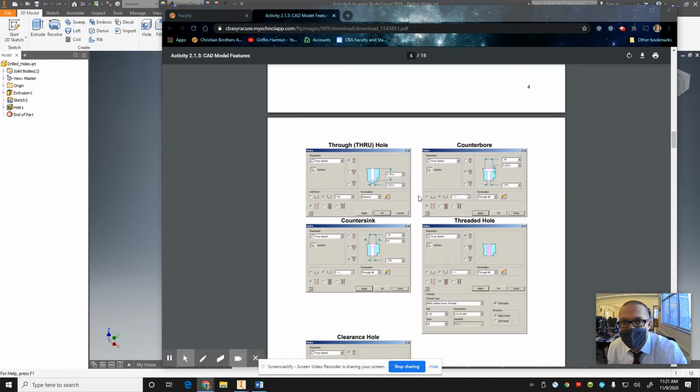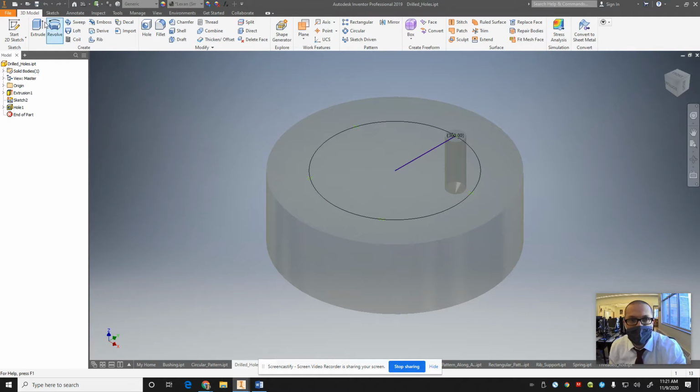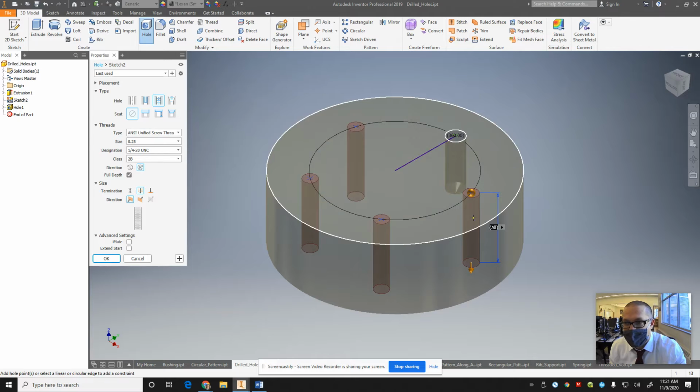So in your 3D model, you hit a hole, and it automatically selects all of the visible points in your drawing. What you can do is hold down Shift and deselect some of these. Now that first hole's in there, probably shouldn't be, right?